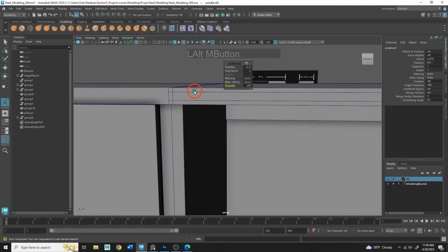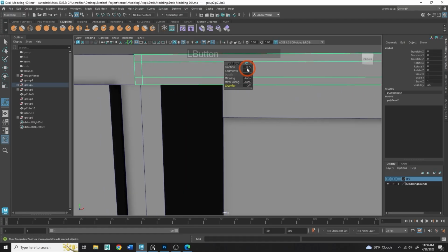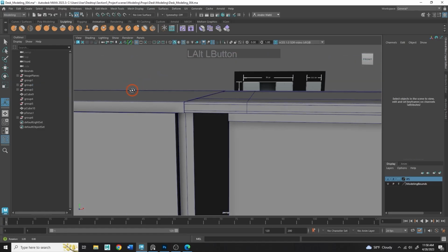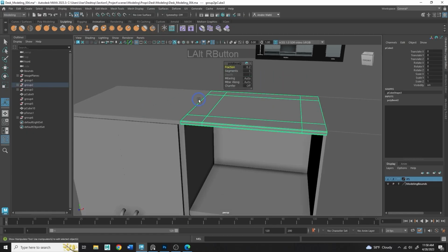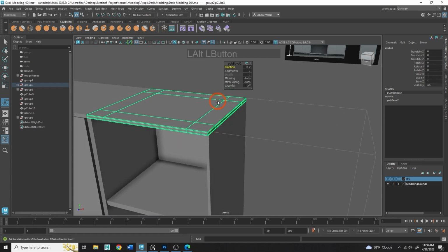And then I'm going to find a fraction that works. Right now, this is a bit round. So I'm going to set the fraction to maybe something like 0.2. And that looks good. If I press 3, that will smooth out nicely. And you'll see what this is going to do is give us that nice neighboring bevel. So we get a good result there. We might want to add some extra edges as we go, but that should do the trick.